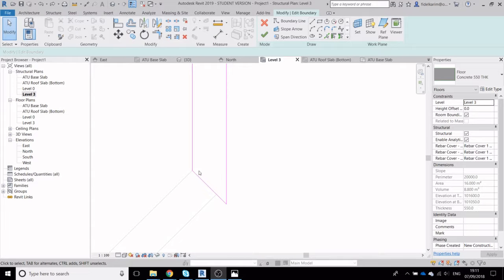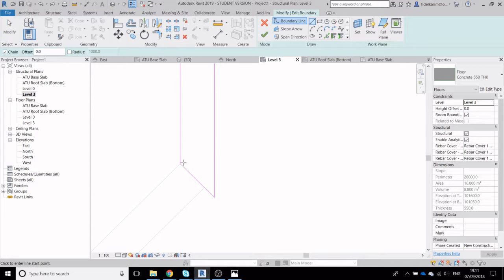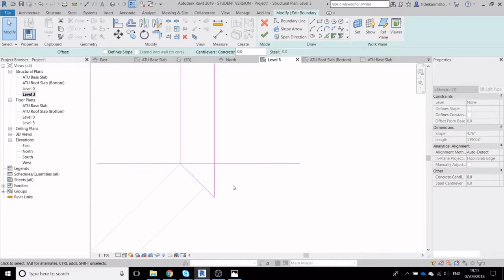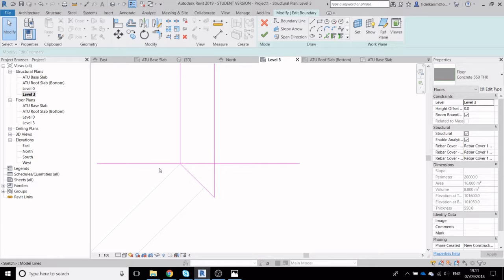Sorry about that. Basically, I wanted a 45-degree angle between the perpendicular line and center line of this, and this angle is basically 45 degrees away from the line there. So if you imagine that this line, that angle is 45 degrees and that angle is 45 degrees. So this one should be 45 degrees, but in order for these to connect perfectly without this issue here, this angle here between this line and that line needs to be 22.5 degrees.